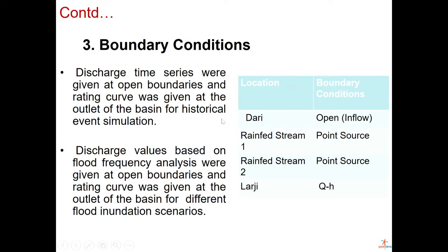In this case, what we have done, I will try to explain. We ran this model in two cases. If you go back to your objective, our objective was to run this model for extreme events of 100-year, 200-year and 500-year return period, right? But before that, we want to ensure that this model is working fine. So we'll run this model for some historical events, and then we'll evaluate whether the model is working fine or not by comparing the simulated and the observed discharge.